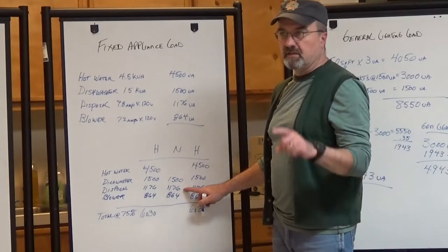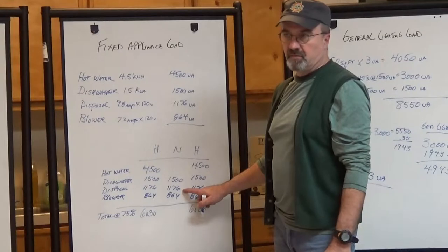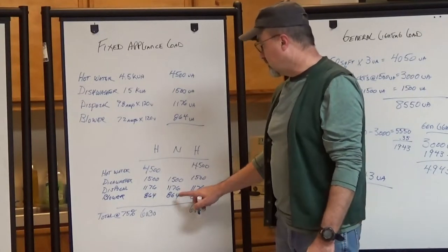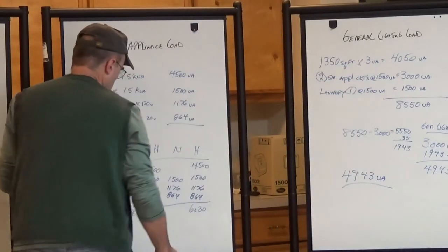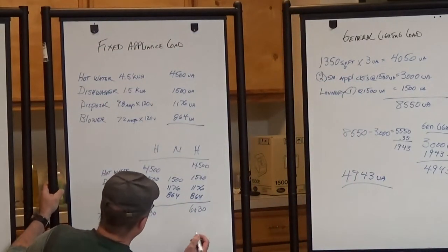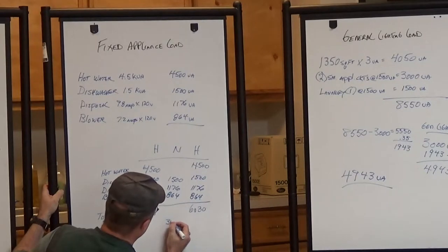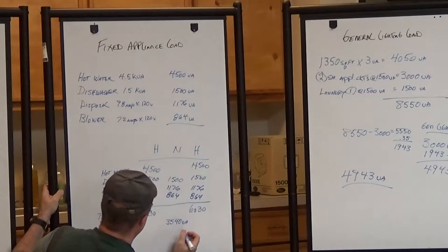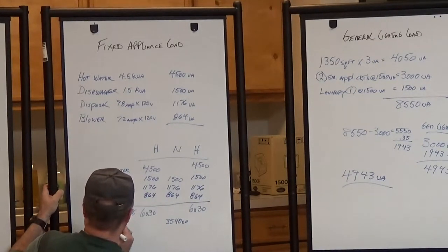You gotta have how many at least? At least 4, right? So the neutral does not have 4 appliances fastened in place. So we have to take the neutral at 100%, okay? So the neutral is going to be what? 3,540 VA. Okay? Total at 100%.